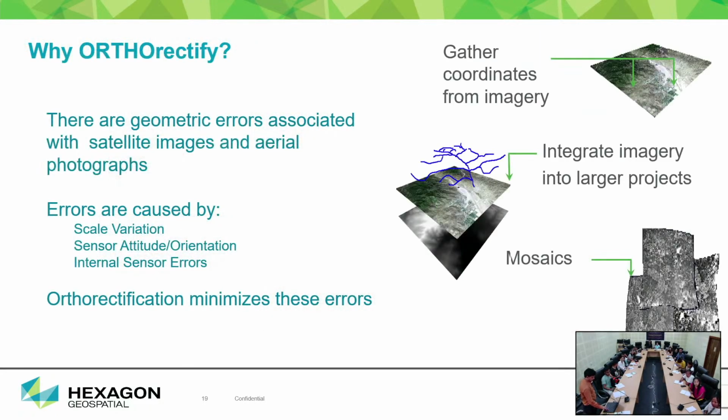Now this will be more clear here, the orthorectification of the image. You can see that I already gave the example of gathering coordinates. Somebody tells you to collect some points from the imagery, so you take some points from the imagery, and it gives the map coordinate values. But once you have georeferencing, you perform the orthorectification of the image using the DEM, digital elevation model.